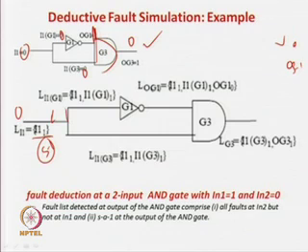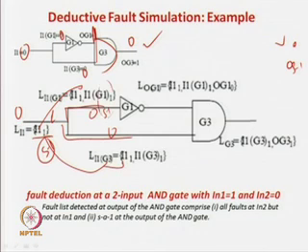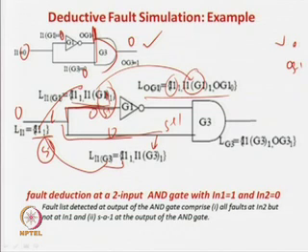Now, the fanout rule. This is a 0 and this is a 0. So obviously, this one gets propagated here, and this one also gets propagated here. And then a stuck-at-1 fault at this net is here, and a stuck-at-1 fault at this net is reflected over here. So this is the case. Now, by the inversion in an inverter, we know that whatever fault list is here will get here. So we have this one and this one which are propagating from this end.